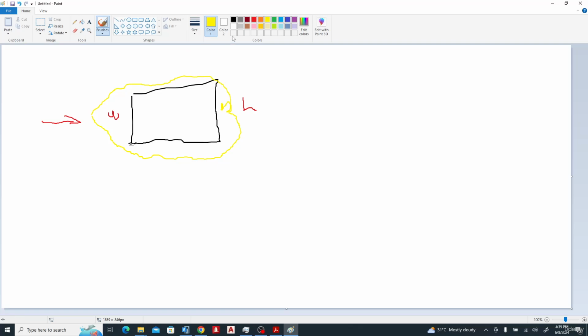Now what it means is we have a coefficient, Cpe, the external coefficient. When you see E, it is external, and when you see Cpi, it is the internal coefficient. Now the wind is coming like this, so it is pushing the windward side. Then at this place it is pulling it apart like this and like this, so this one cancels this one, so it is 0. This one balances this one. I hope you understand. Now in this place it is a pull. So if this is push, this is pull.